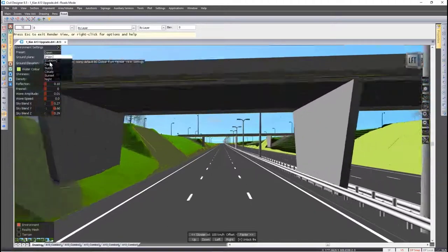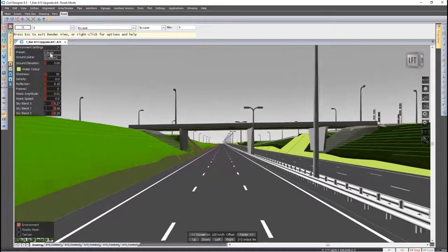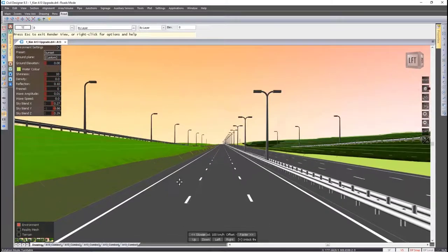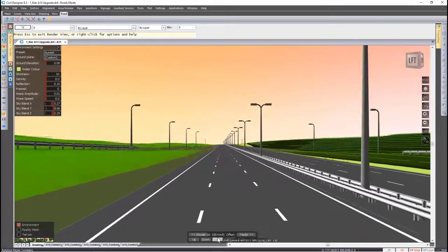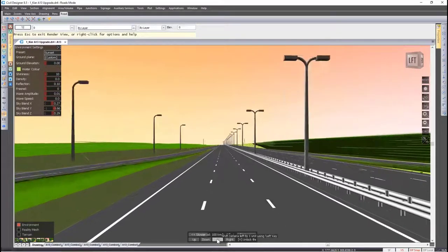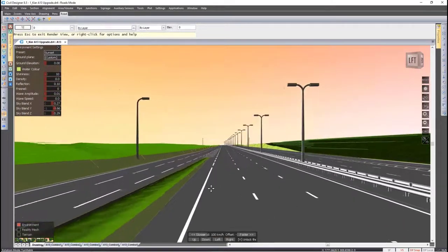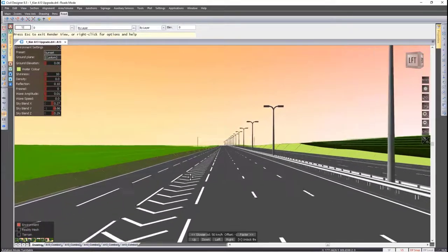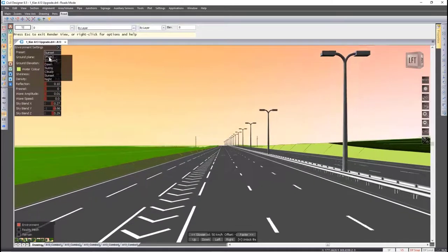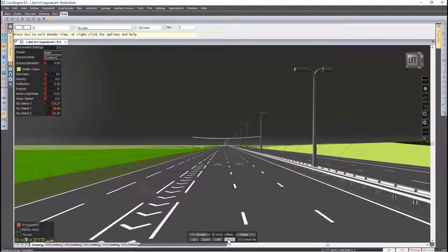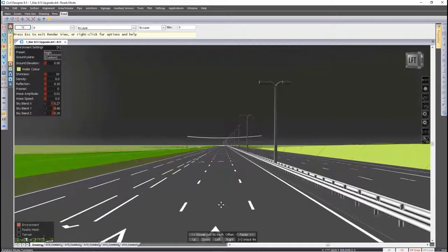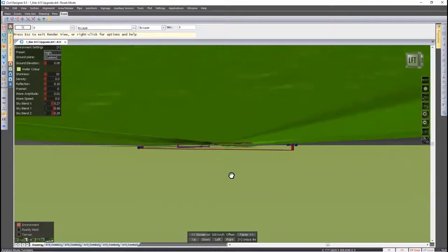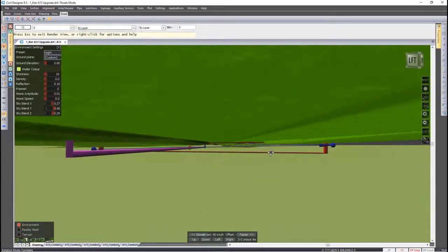Carrying on with our environmental settings, and as we approach this on-ramp onto the highway, these road markings can now easily be inserted by using the new drape hatch functionality found under the road's signage menu. Changing my environmental settings and moving to the right. As we approach some crossing surfaces, I'm going to go beneath the ground. Looking at these pipes, I'm going to slow things down somewhat.